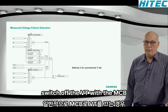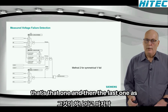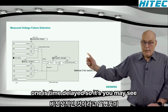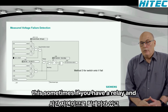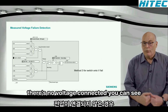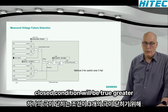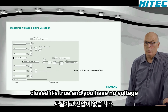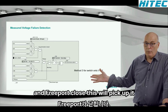Typically, if you switch off the VT with the MCB. That's that one. And then the last one, as I said, the switch on one is the unusual one, is time delayed. So you may see this sometimes if you have a relay and you simulate the circuit breaker auxiliary contacts to be closed and there's no voltage connected. You can see the one pole open or one pole closed condition will be true. Greater than one pole closed, typically 3 pole closed is true, and you have no voltage.